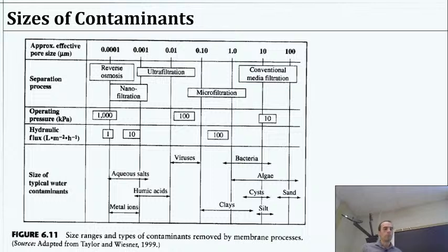Okay, so last thing I'm gonna just go over real quick is the size of different contaminants. A lot of our removal processes will relate to the size of different contaminants in some manner. So whether it's filtration or sedimentation, the capability we have depends a lot on the size. So larger particles will settle faster. So if we are doing some sort of sedimentation, usually what we'll try to do is have some sort of coagulation, let them grow bigger, settle that way.